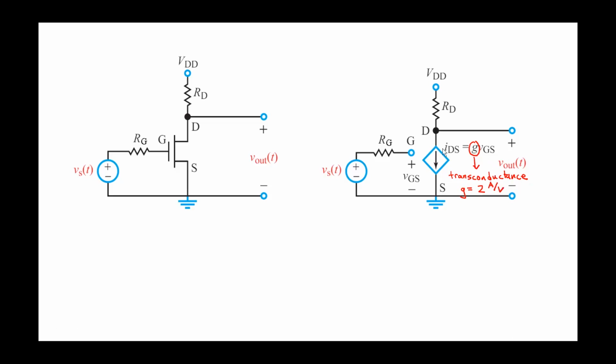So this equation, by the way, implies that there's a linear relationship between the drain current and the gate voltage of a transistor for any voltage. Now, this is not the case for MOSFETs. In fact, large DC voltages in general don't have this linear mapping. But for this problem, we just want you to start thinking about what it means to be a voltage-controlled current source. So just keep that in mind, that it's not always a linear relationship. Okay? So that's what's going on over there.